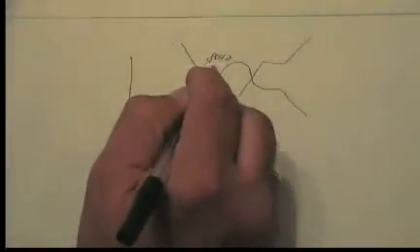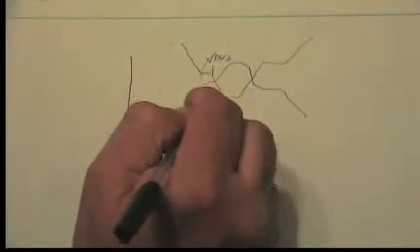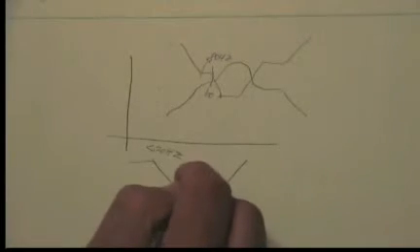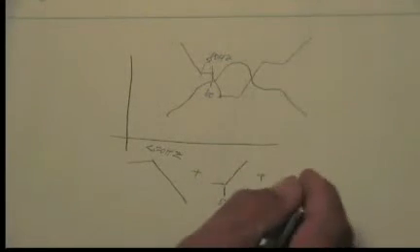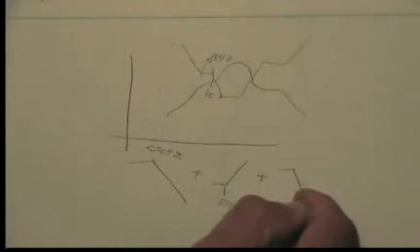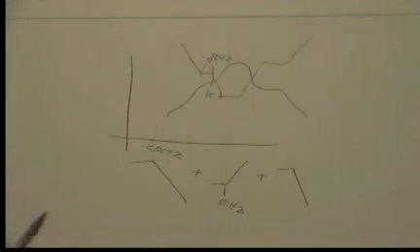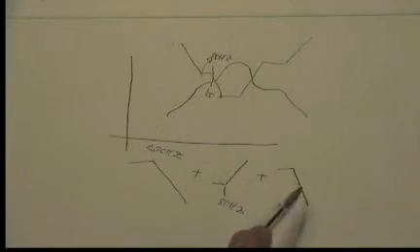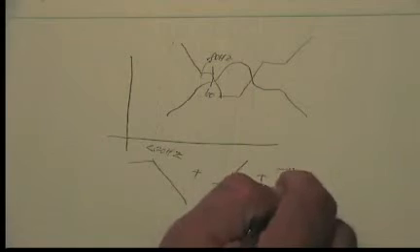Then a little bit later, at maybe 100 hertz, I want to start falling again. And so this one plus this one plus another low-pass filter, which looks like it might be about the same slope as the first one, but at a higher frequency, at about 100 hertz.